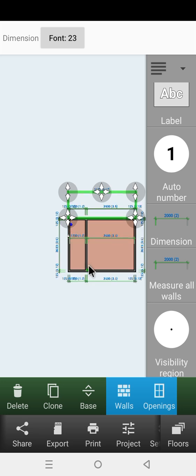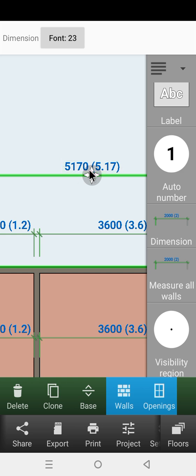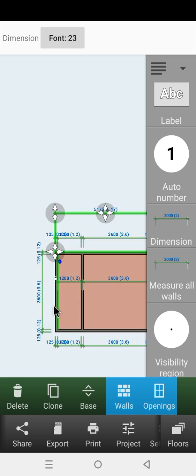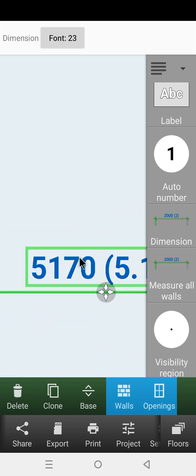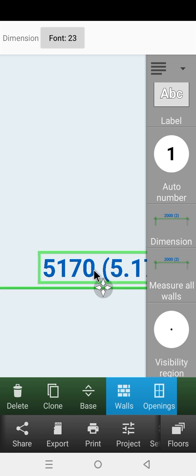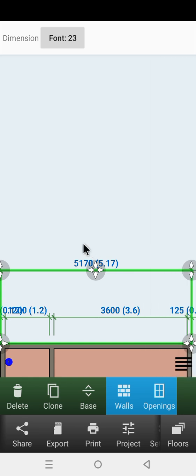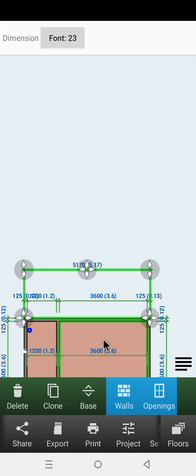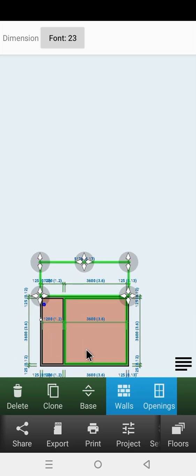If you are using 6 inches or 8 inches, this total dimension for the measurement will have to increase. So if you use 5 inches block to design your plan, and only get to the site and find out they are using 6 inches, your total dimension for the building will be different, and they will have one thing while you have a different thing on your paperwork. That's why I hope you see the essence of why it is very important for you to know the inches of block they are using on the site.